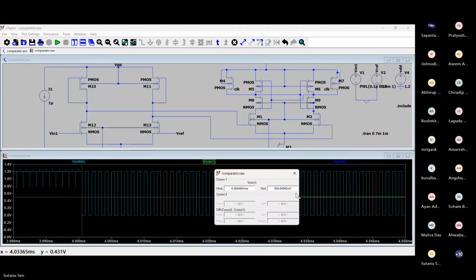Here, definitely, once you improve the gain, once you add the gain stage, it will do the amplification of the difference. The difference applied to the comparator stage gets amplified. As a result, it will be able to resolve smaller values. So this is shown here by the simulation. You can see in the earlier case, it was still uncertain.